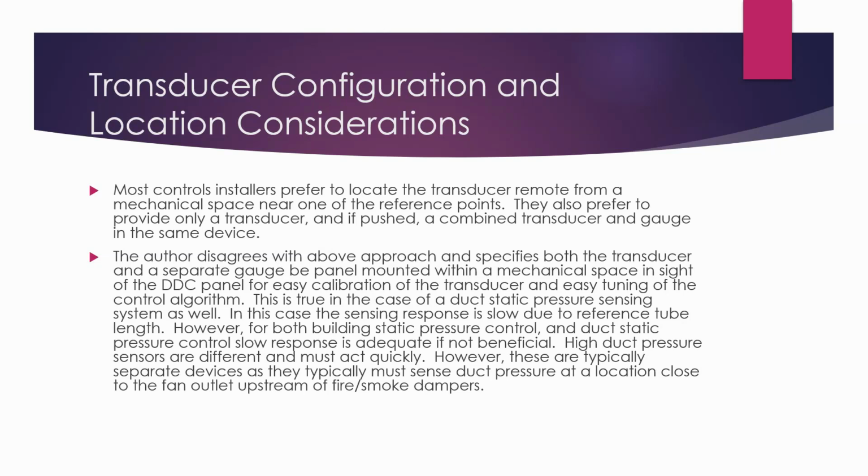However, I think that's a lousy idea because they're easy to get lost. They're not near the DDC controller, and so if you have to calibrate the transducer, it's hard to calibrate it. So I make it a point to specify it differently.